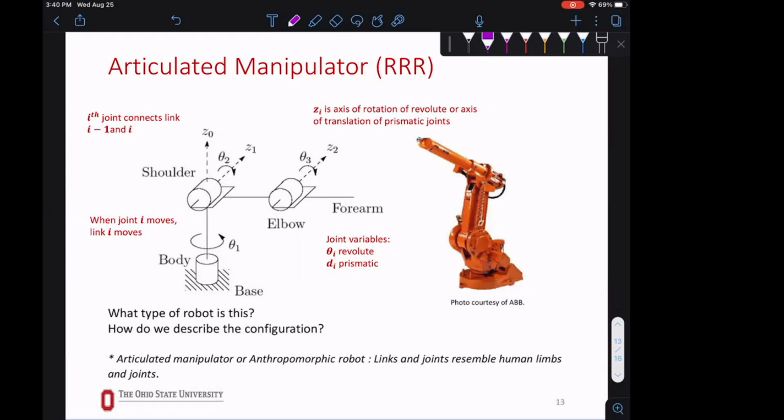So every time you see a joint, there should be something connected to it, unless there is an end effector at the end. Sometimes for simplicity, we don't show the end effector. We just say, for example, the forearm, there is going to be something after. We cut on purpose, but we know something is connected. So when you have 6 degrees of freedom, we usually say, okay, let's just build the elbow and a wrist. So 3 and 3, let's make things simpler.